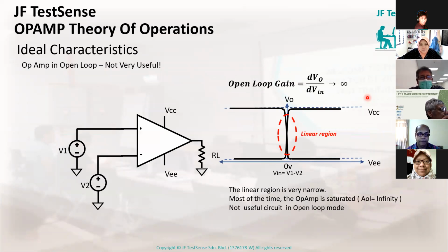So when you apply an op-amp as an amplifier, you only want to apply it in the linear region of that device, correct? Because you don't want to apply it when the device is in saturation at one level or the other, right?